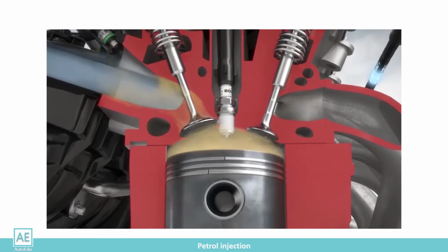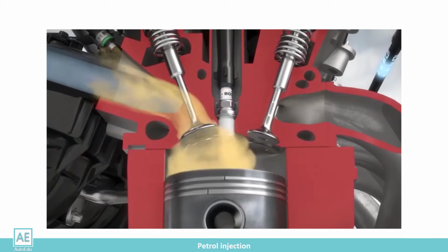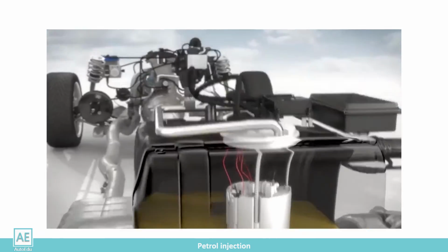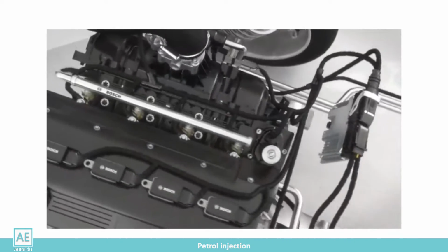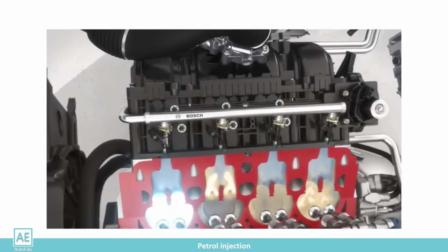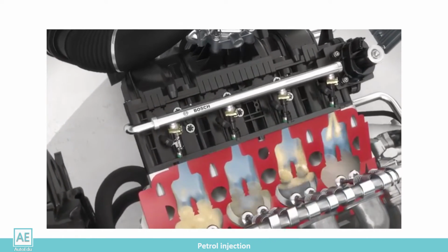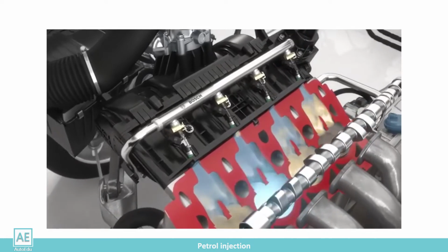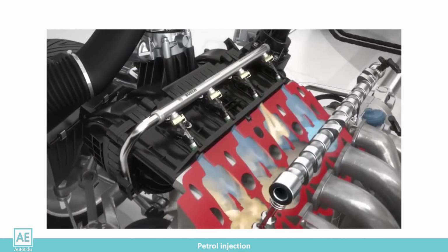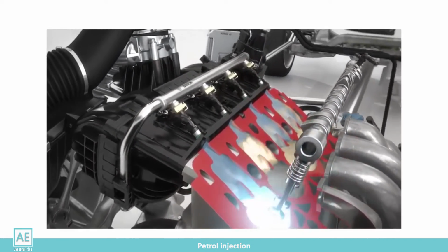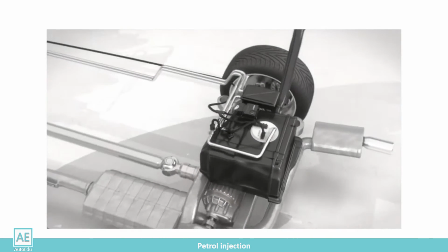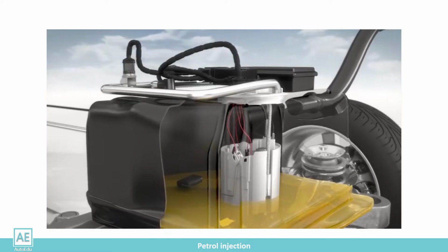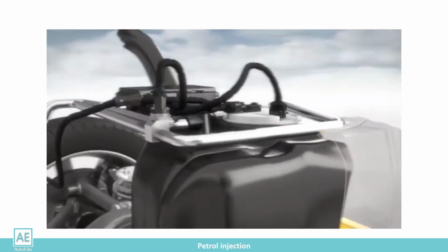The correct and efficient operation of the engine depends on the correct amount of injected fuel. The fuel supply system consists of several elements that participate in the delivery of gasoline for injection. All elements in the fuel supply system must function correctly and be coordinated with each other. The tank is an element that stores fuel, and the pump pushes it through the system to the injectors that inject at the mixture's formation point.